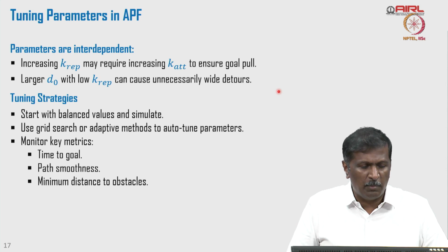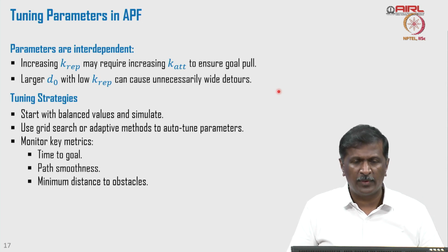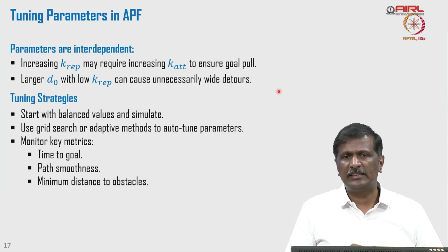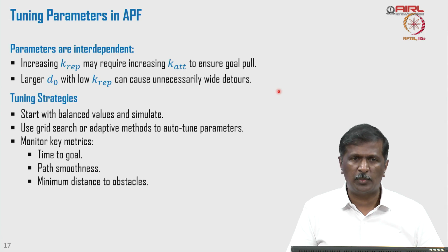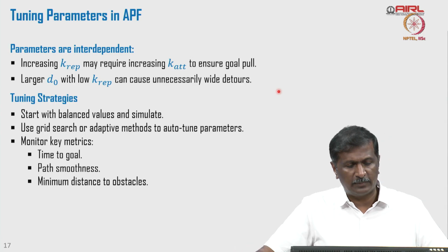Or I can monitor key metrics. What is the time to reach the goal? How smooth is the path? What is the minimum distance that I always keep with respect to obstacles? I can use these metrics to fine tune the parameters.